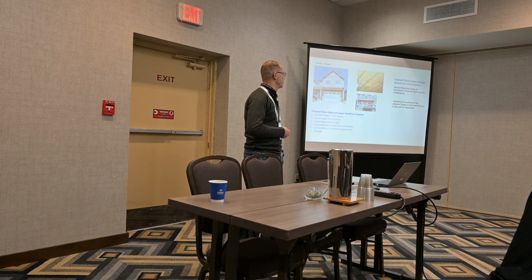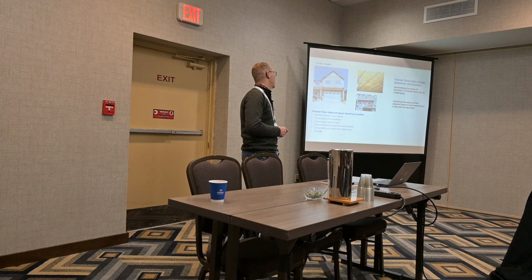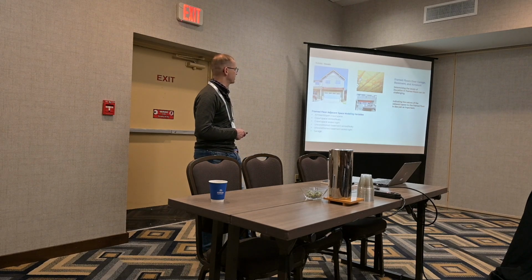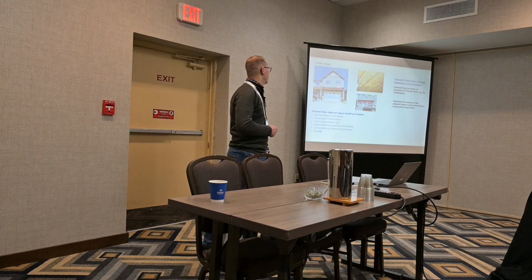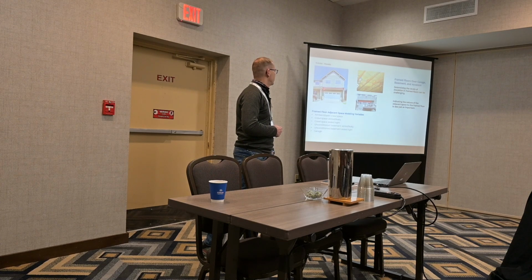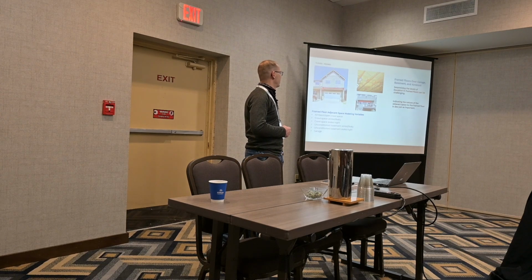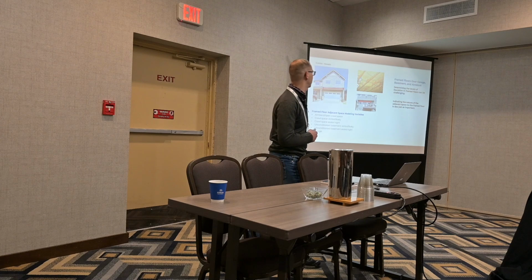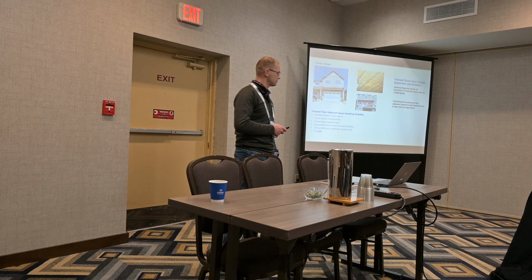This floor should be insulated per best practices and some building codes, but make sure you double check how far that is, get good measurements, and what type of insulation is installed in there. Framed floors over garage and basements and outside. For that type of building, best practices and building codes require this to be insulated and separate the upstairs from the downstairs, but once again, make sure that is correct and get that measurement so you understand the R value for that space.